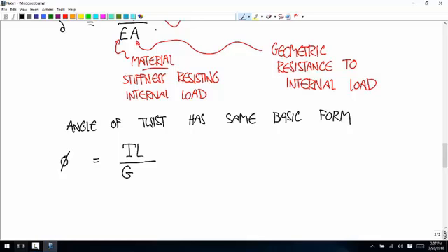Area resists tension or compression. It wasn't the area moment of inertia, that resists bending. It's a third one. I sub P, polar moment of inertia. Oh yeah, of course. If you go back, you can see that that's all based on geometry, and it gives you a resistance based on the geometry to a torque.